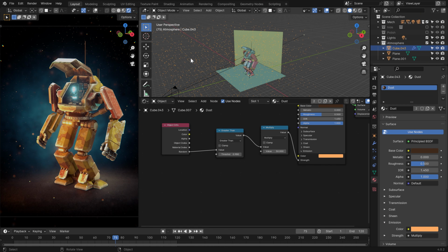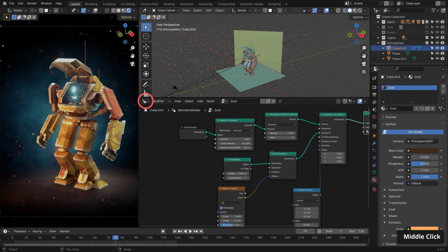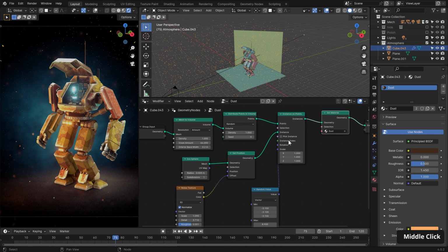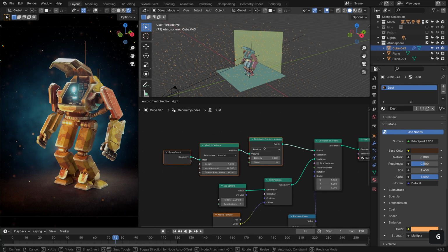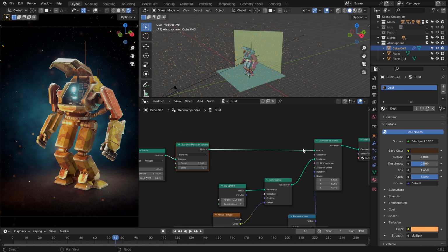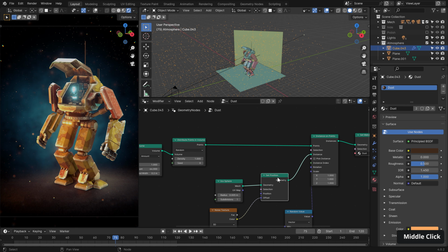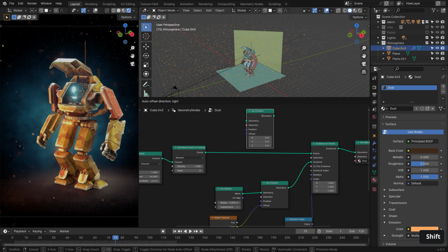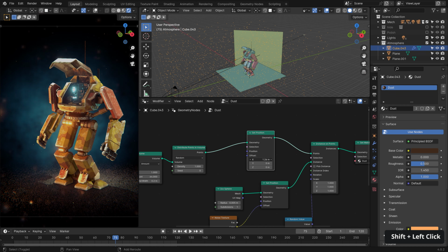So in order to animate our geometry nodes, we need to switch ourselves back to the geometry node editor, and we need to affect the position of our points. So if we move these 3 nodes back, this is the area we are working within. And we can use the set position here we've already created by Shift and D and moving it up here.